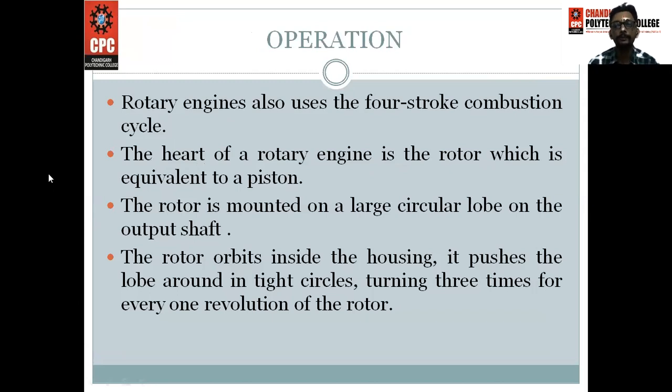Operation: the working operation of the Wankel engine. The rotary engine also uses the four-stroke combustion cycle. The heart of a rotary engine is the rotor, which is equivalent to the piston. The rotor is mounted on a large circular lobe on the output shaft.